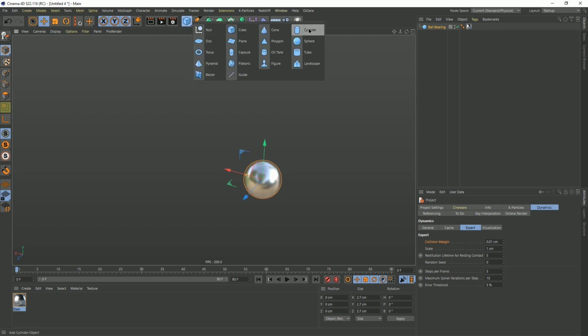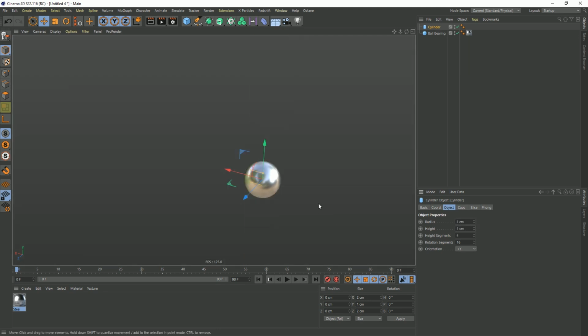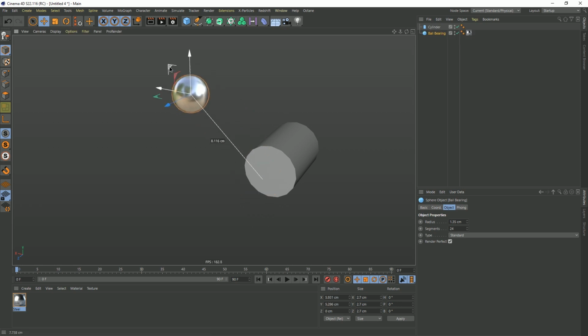First of all, we can make something to visually represent the motor. I like doing that just with a cylinder. I'm going to begin a lot of my objects by setting the radius to 1 just to make it approximately the right size, and then we can scale it up from there. Z plus for the orientation, and for the motor, let's just increase that to be about that. We'll probably change it in a little bit. This ball bearing is going to get in the way, so I'll scoot it away.